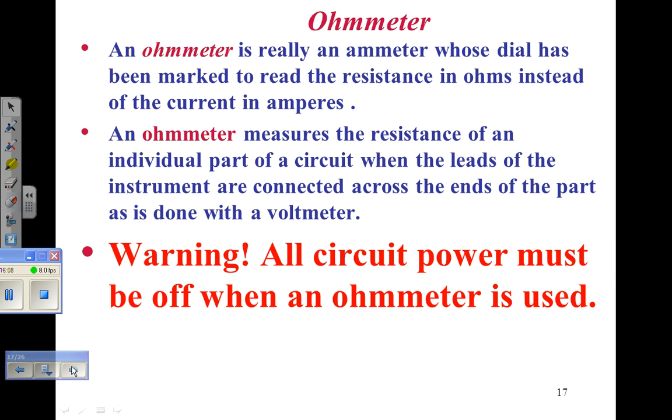And because of that, when you go to the second semester and you buy a meter, you're going to buy a really good one, but you're going to buy one that has 2 fuses, one for the current and one for the rest of the meter. And it is much better to burn up a fuse than a meter. Okay?